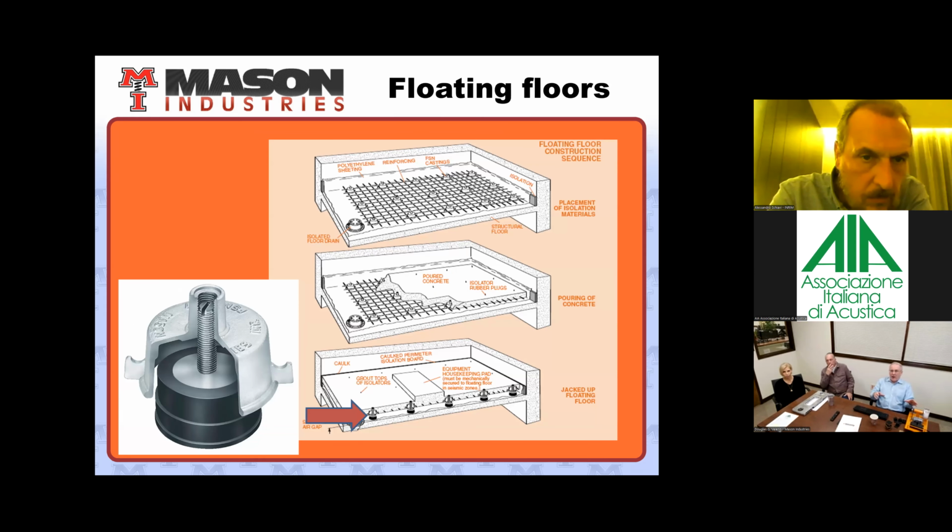We talked about vibration isolation, but as you can see with this fan, it creates a lot of airborne noise. So we have systems, both floating floors, walls, and ceilings, to reduce that airborne sound transmission. Don't really have the time to get into that in any depth, but know that's available, where we can create an isolated room within a room to reduce the sound transmission.